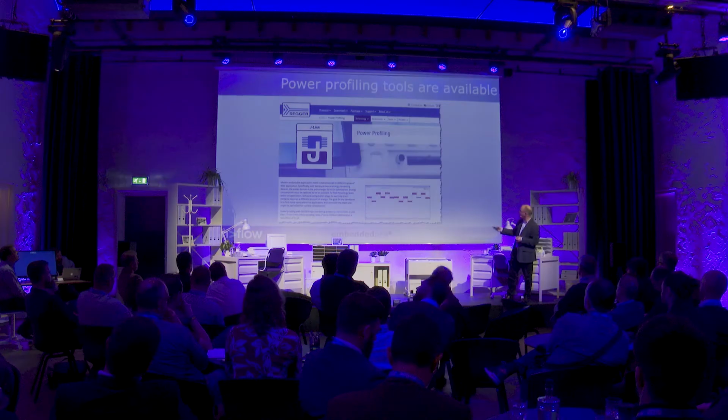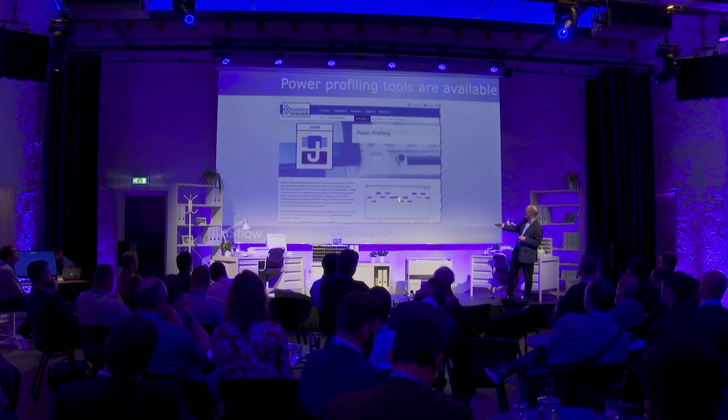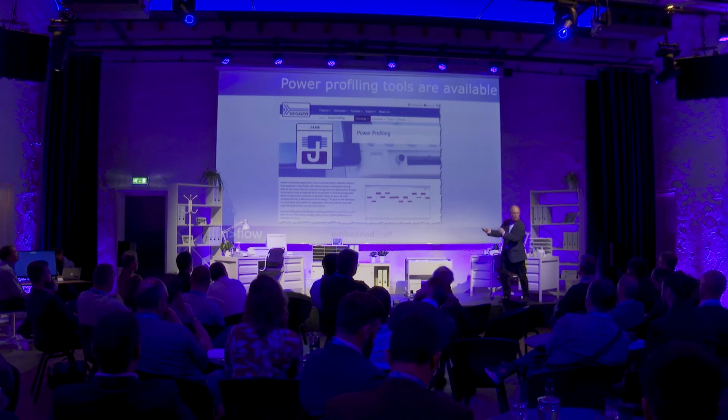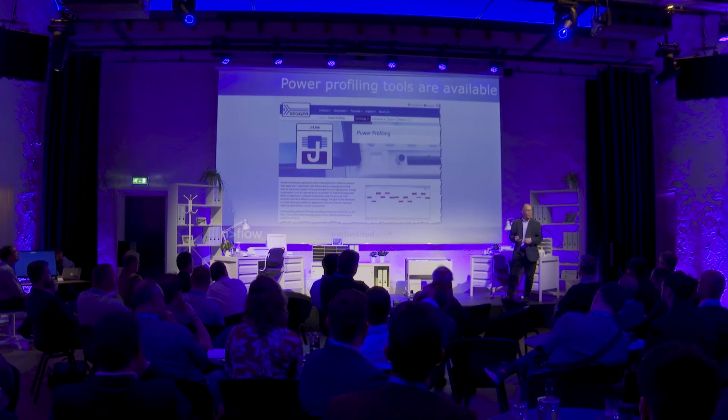From an embedded point of view, power profiling tools are available. Whilst you're doing your software debug, some probes, and here's my friends at Segger, they offer debug probes that can actually measure the current that the board is taking whilst you're in a debug session. And that's great because you can actually see where code is running and how much current the microcontroller is taking right there and then. It gives you a very good feel for how much current the micro is taking.